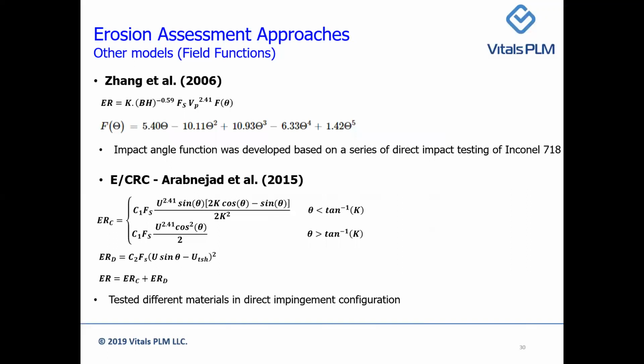So we need to define this sharpness factor in the equations. The next question is, can I deform a boundary based on erosion rate? Yes, you can couple the mesh morpher in STAR-CCM+ to a boundary erosion rate value to deform the eroded boundary. So yes, it is also possible to use deform mesh.